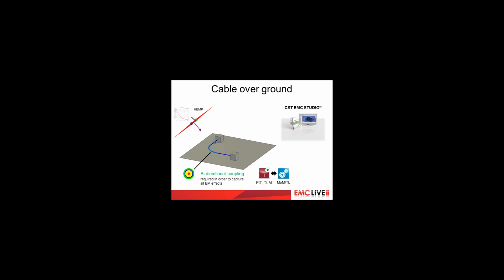So CST EMC Studio is an ideal tool for simulating problems like this. This software package includes CST's 3D transient solver and Cable Studio solver, which may be used together in a co-simulation, or essentially as a hybrid method, to simulate a wide range of EMC problems. And Cable Studio enables the complexity of cables to be modeled without using a fine 3D mesh for the field solver. This hybrid approach can also be bidirectional, which means there is communication both ways between the field solver and the Cable Studio solver at every time step.